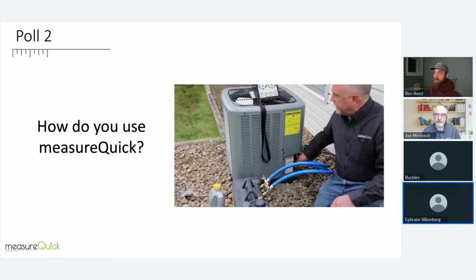And so the word approach would be what you want it to be. That would be the baseline. When you say the word approach, what do you mean by that? So yeah, the approach is the temperature of the liquid line compared to the outdoor temperature. That's the definition for us of approach. When I do my demo, I'll bring up approach and you can see how you can read what we have in the app to do that.